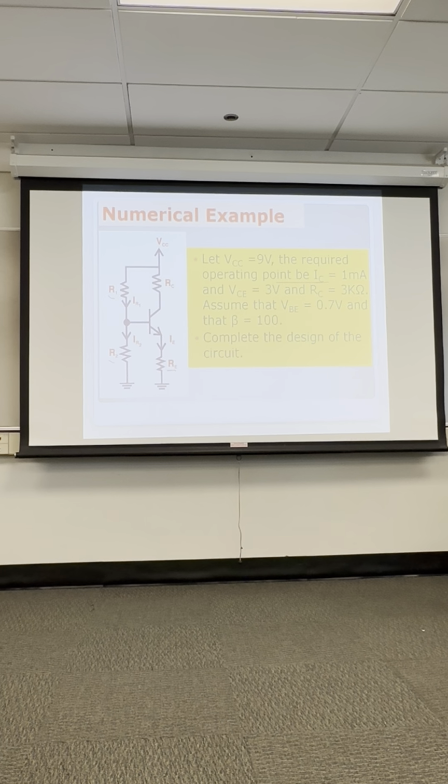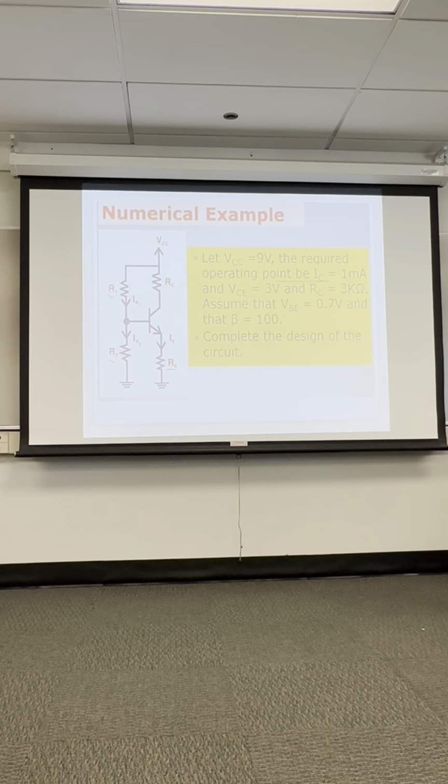And then what's given though, collector current is 1 milliamp, and the collector emitter voltage, once it's designed for an operating point, is equal to 3 volts. The battery is 9 volts. Now, we can't solve for the base current, we do not have resistors R1 and R2.